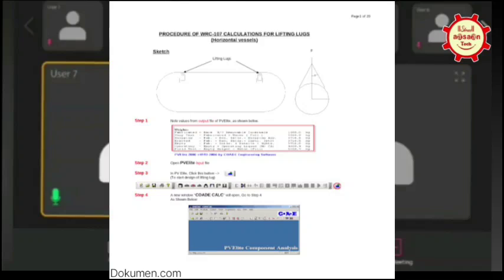Correct. And the second question is about the loads on the nozzles, right, Abhishek? If the loads are high and the piping people are saying that they cannot be reduced, you can try one of these methods.